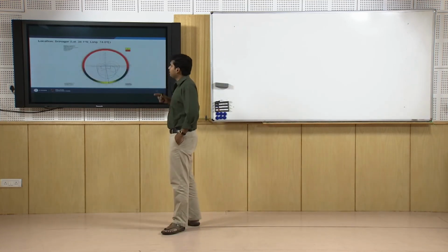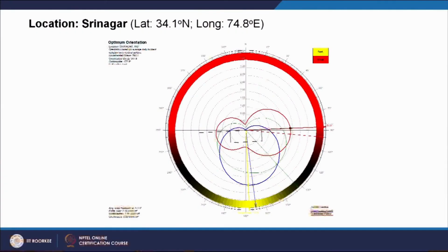To get a better understanding, we have this graph. The small rectangle box here represents a building's orientation. The red lines indicate the solar radiation during summer, depicted as the overheated period. The blue ones indicate the solar radiation during the underheated period, or the winter season. This is an interesting graph which shows the major direction from which higher solar intensity comes during summer, this is during winter, and the green one is the annual average.